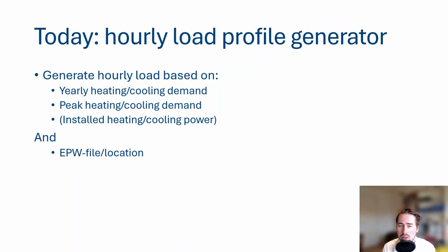An estimation on the peak heating and cooling demand, which you always have to do. And then we added another option, which I will discuss in a bit, related to the installed heating and cooling power. So based on these inputs and a weather file, an EPW file, or you can also enter your location and then we will extract the information from there, we can create for you an hourly profile.